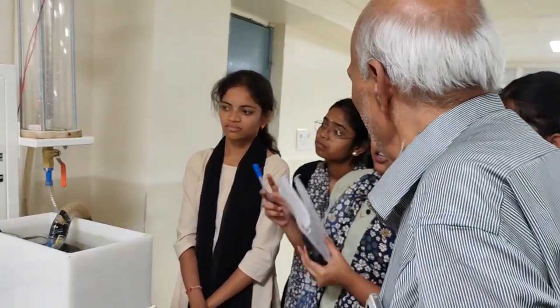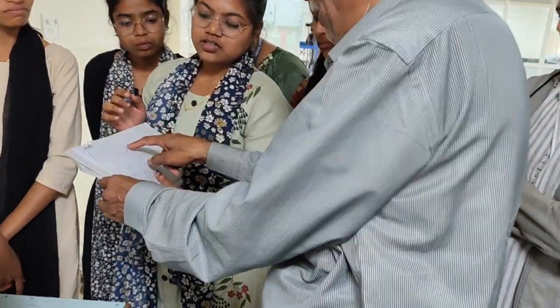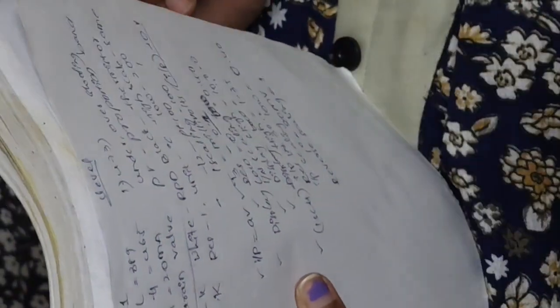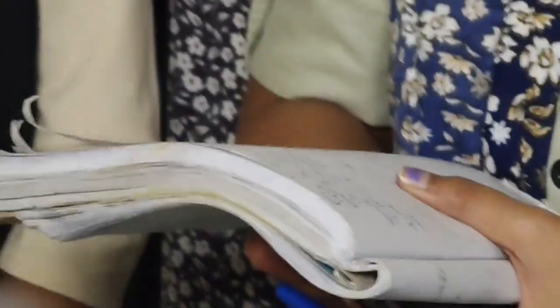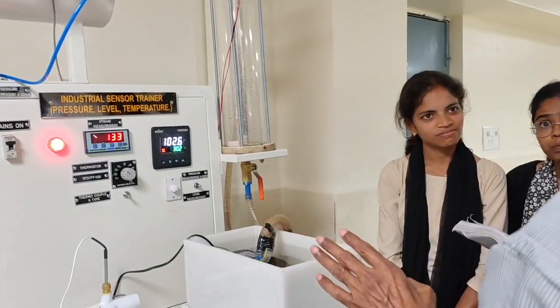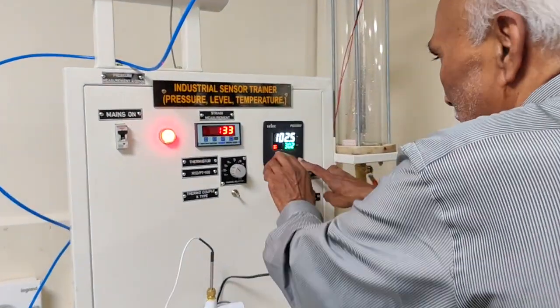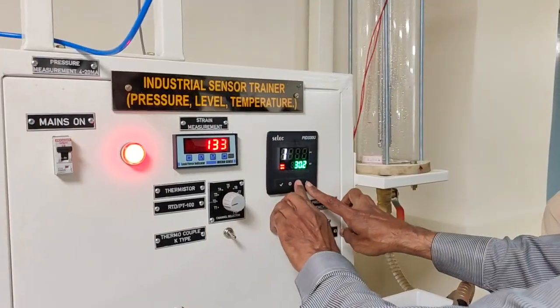For the thermistor, we have to set all these values. Only for 10 volt you have to set input, 0.4 and 1.35. These three, because it is calibrated for that particular value. Other things are 4-20 standard. You can read directly. Only for the thermistor. For K type no need to set. Only set it as K type in the program. When you go to the level, I'll tell you.